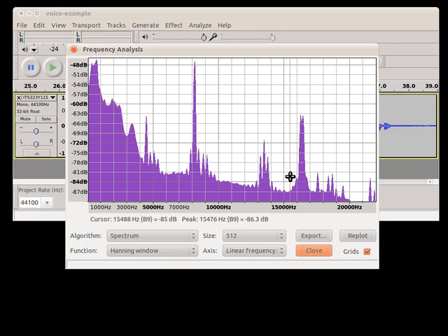So this is a plot of our signal. Looks something like this if I drew it in a linear scale. The peak is concentrated in this range of the spectrum. Then it gets much weaker. Even though it looks like it's quite high here, it's very, very small in a linear scale, because this is a decibels or a logarithmic scale. So the point is that most of the signal strength is concentrated in this area of around several hertz to 3,000 hertz. And that's the frequencies that voice are mainly concentrated in.